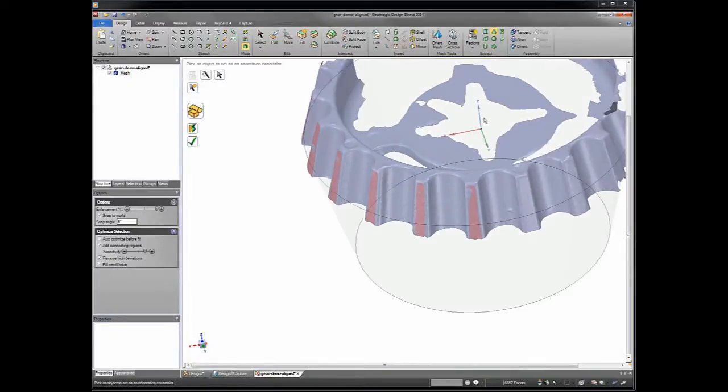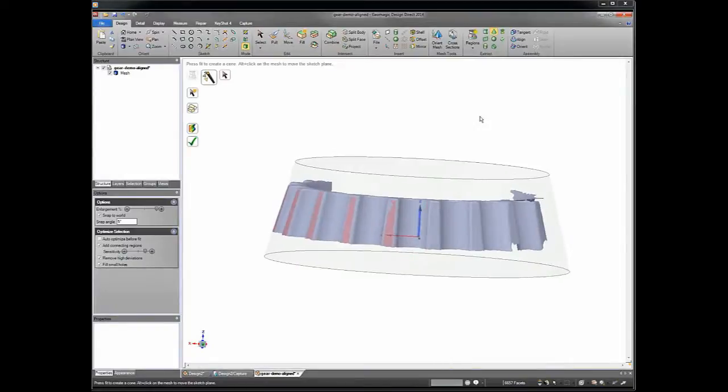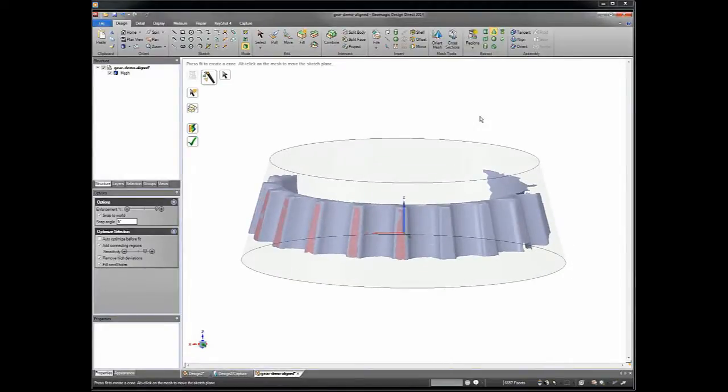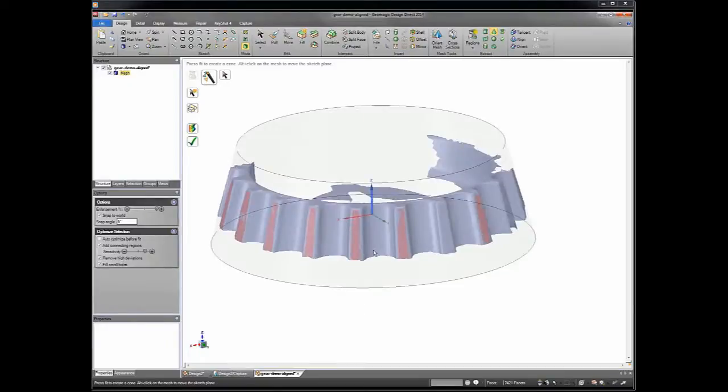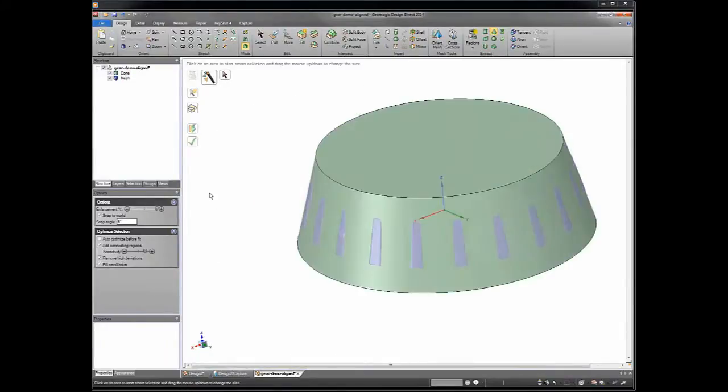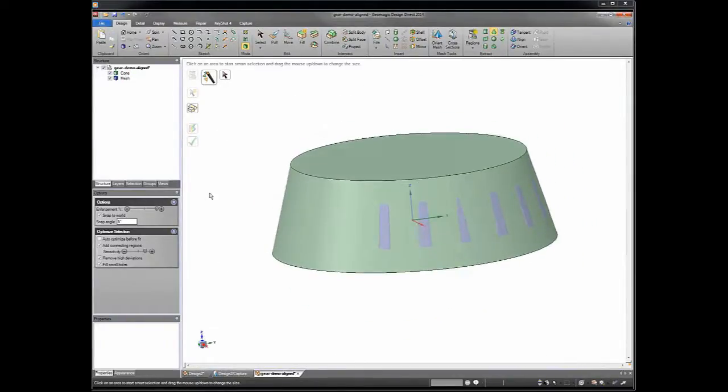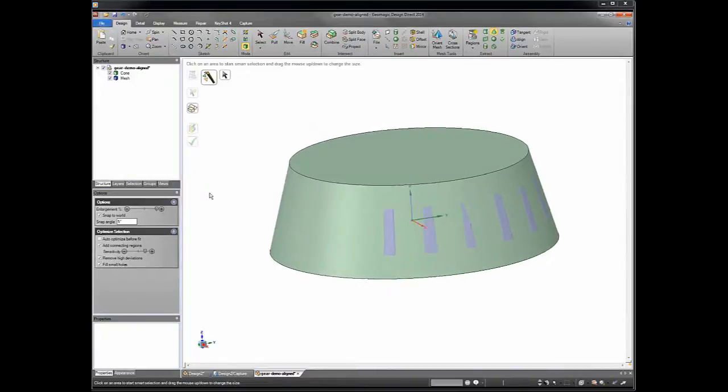And the other thing I can do is help it out by giving it the rotational direction. So eventually you see there that ghosted shape. It's showing me I'm slowly defining it. And it's probably a little bit of overkill if I keep adding more on the side. So I just go ahead and click the complete button, and I've got kind of an oversized cone.